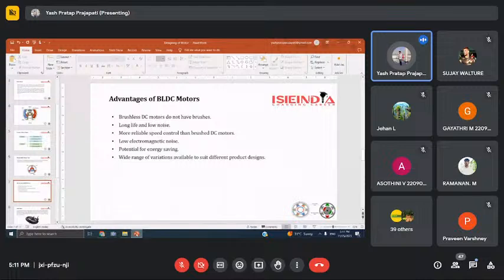One big advantage is efficiency, as these motors can operate continuously at maximum rotational force, or torque. Brushed motors, in contrast, reach maximum torque at only certain points in the rotation. For a brushed motor to deliver the same torque as a brushless model, it would need to use larger magnets. This is why even small BLDC motors can deliver considerable power.